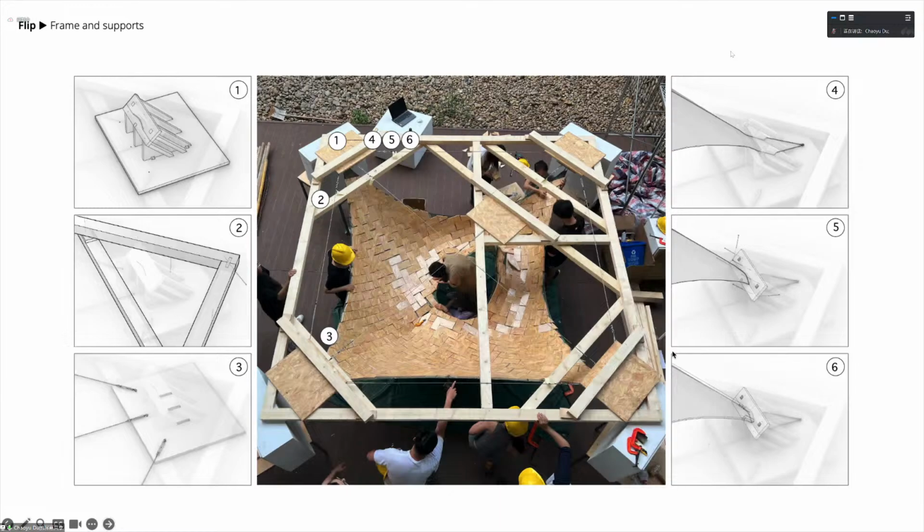The next step is to attach it to the support and the wooden frame. The fabric and the ties are suspended using 5 support structures constructed in waffle, which is shown here. The waffle structures are made of OSB boards with a thickness of 80 millimeter. And the reaction forces in the supports are balanced by the tension ties. You see them here. Also, to prevent any shifting or displacement during the flipping process, the 5 supports are anchored to the wooden frame, which you see here.